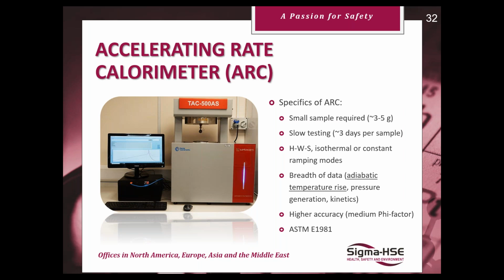This is a slow test because of the heat-wait-search method that it uses. So this can take 3 days to complete a test. But the heat-wait-search method does give very accurate onset temperatures for thermal decompositions. So a safety factor of an ARC test might be 20-30 degrees, whereas with a DSC, it's up to 100 degrees. So it's slower, but it gives much more accurate data in terms of